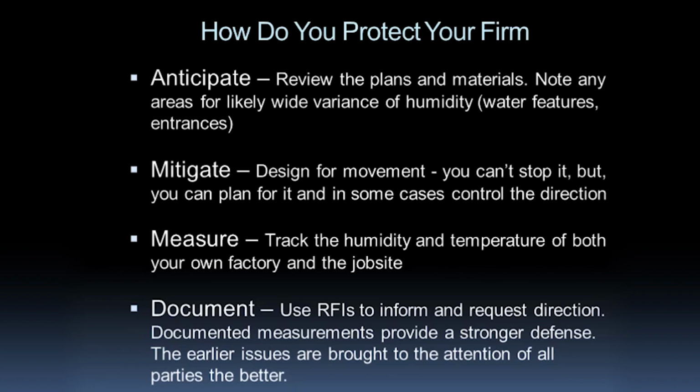And you're right. If you allow the material to get on site and acclimate to whatever the environment is there, it will stabilize after a period of time. It will reach equilibrium with that environment, whether it's got more or less humidity than what your plant had.